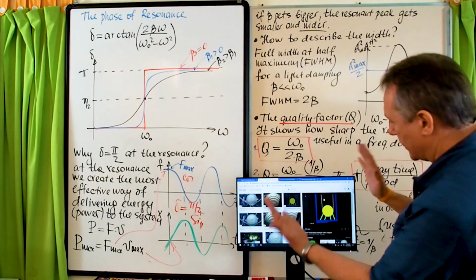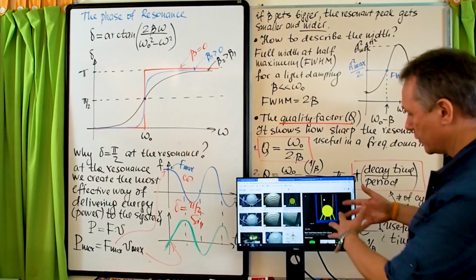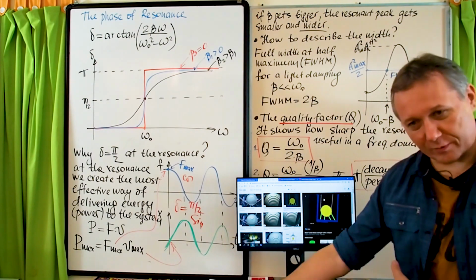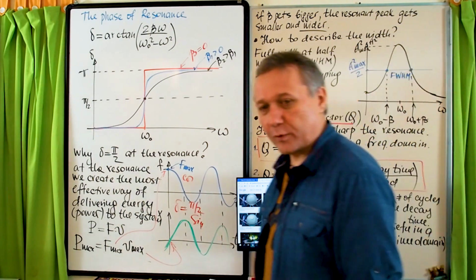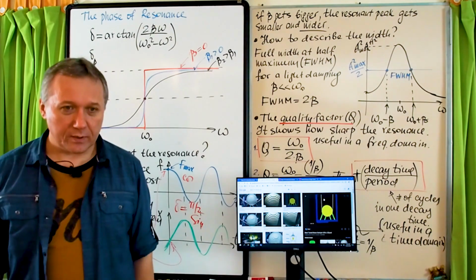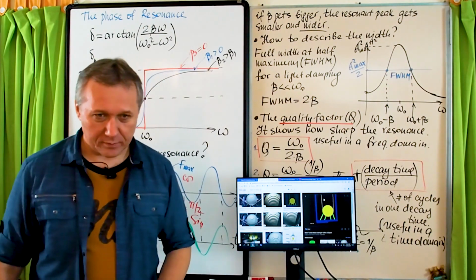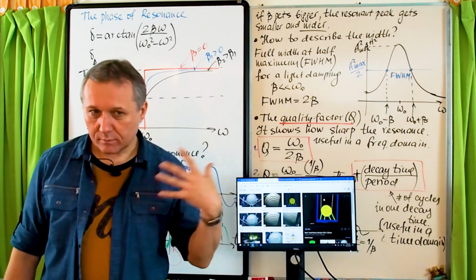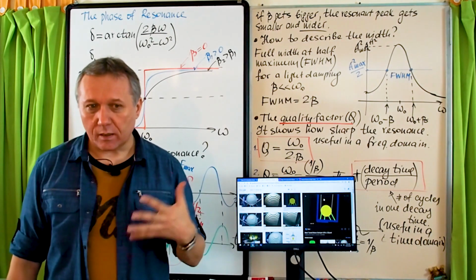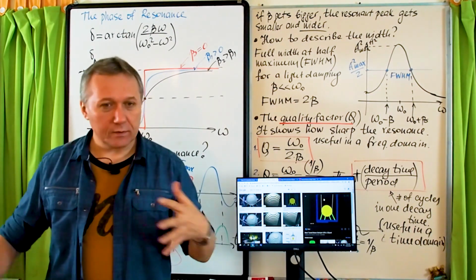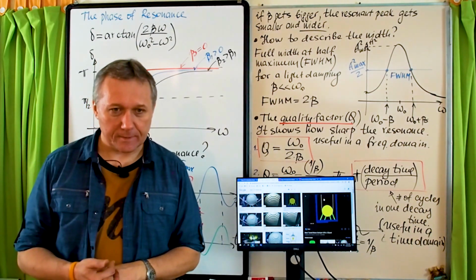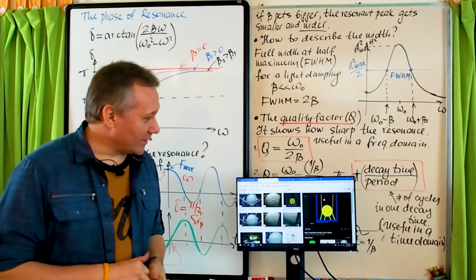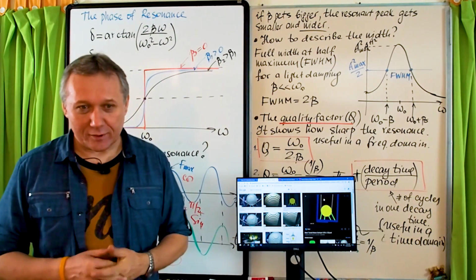If the building tries to move to one side, those springs on that side will get stretched, and they exert additional force on the building, adding additional damping to the system. As a result, the system can avoid reaching large amplitude, so we can avoid getting into the resonance and destroying the system.